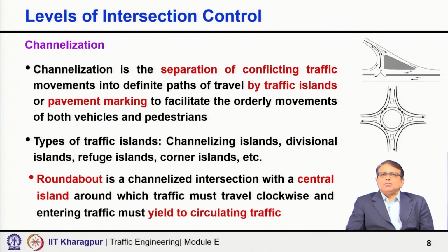Next, often such intersections are also improved further, particularly to improve the safety performance, by providing channelization. Channelization, of course, sometimes may be done even for intersections which are controlled by level 1 control or passive control. There also sometimes you can provide channelization.